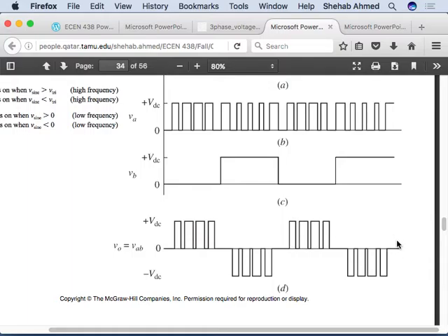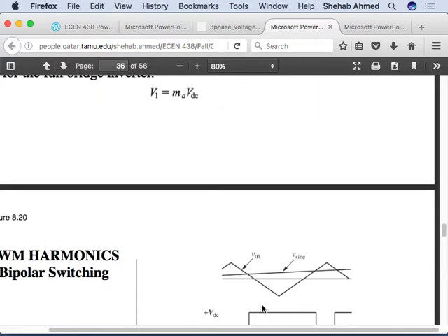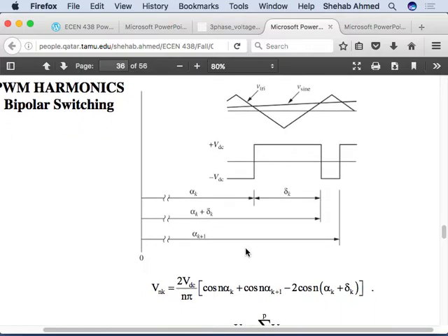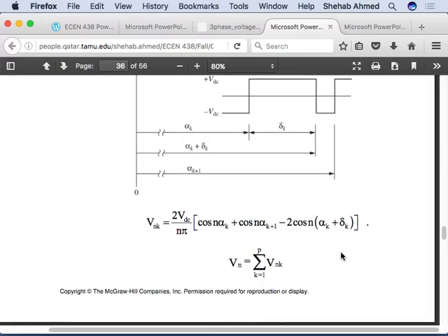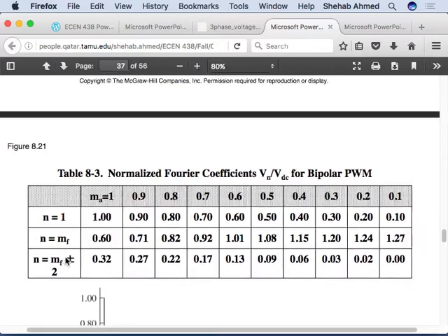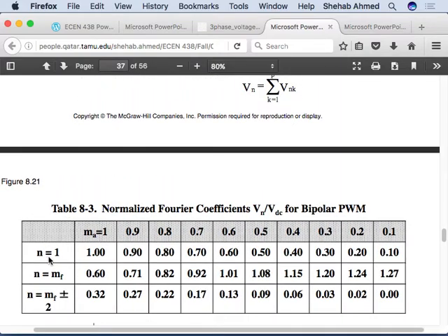So it's a periodic pulse that is defined by a few angles. These angles are what we've defined here. So for that single pulse, I found the Fourier series. Now I want to find the Fourier series for the full waveform. I have to add the Fourier series for all the pulses together, right? Because after that, I can tabulate. This is what? This is V1. This is V for n equals 1.